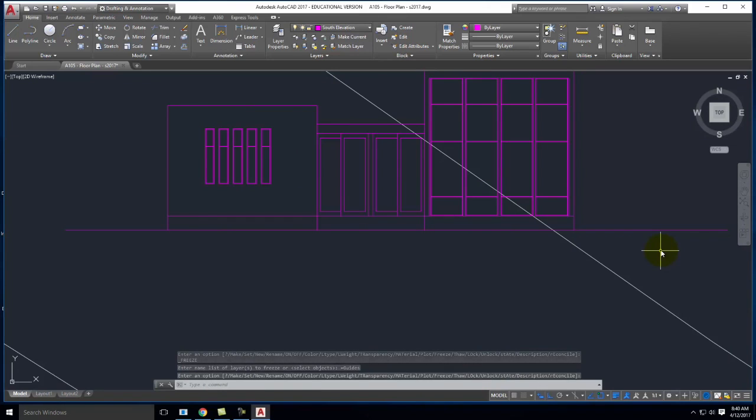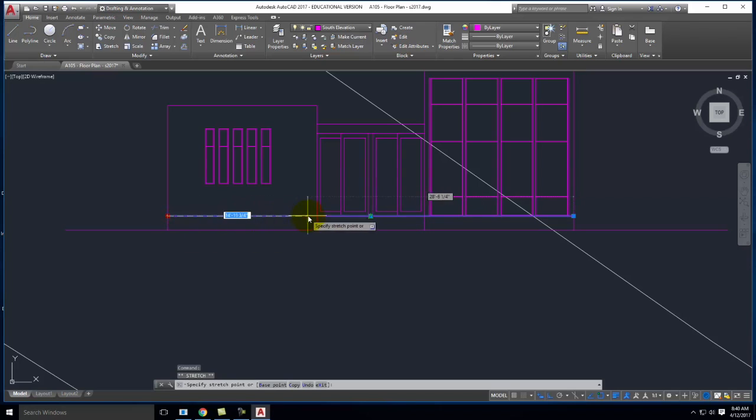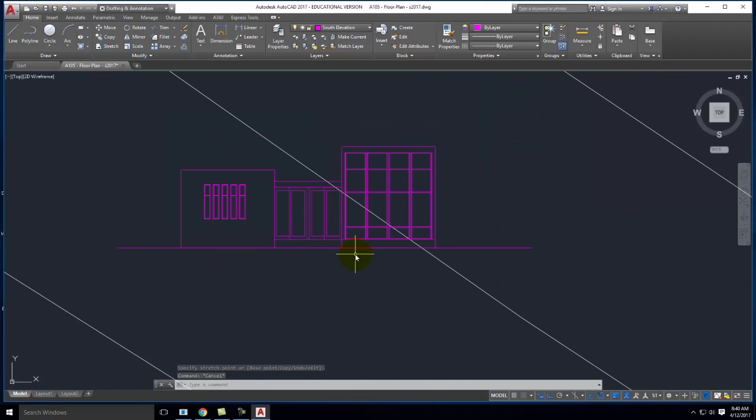And if I turned off the guides layer here, we could now see what's happening in the building itself. Now in reality, this line that represented the floor of the building, unless there's a door where I can see the floor of the building, it wouldn't exist. So for example, this would get shorter to there, and this would just come all the way down on the outside of the building. This we would see because there was a little lip. Likewise, we'd see over here there's a little lip. So we'd still see the floor in those two places. And so now I have a drawing that looks reasonable from an elevation standpoint.